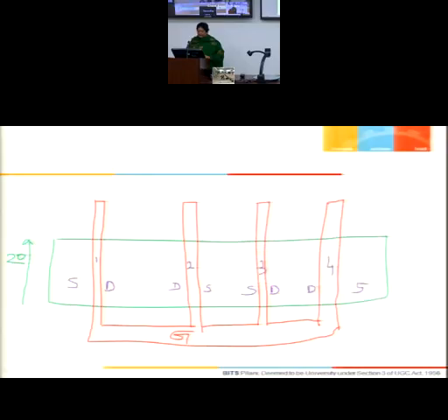So here you have to have a blue line, blue metal, and this is blue metal. And you have to make a contact here. I am showing it by putting a cross. A contact between green active and metal 1. Similarly, a contact here between green active and metal 1.